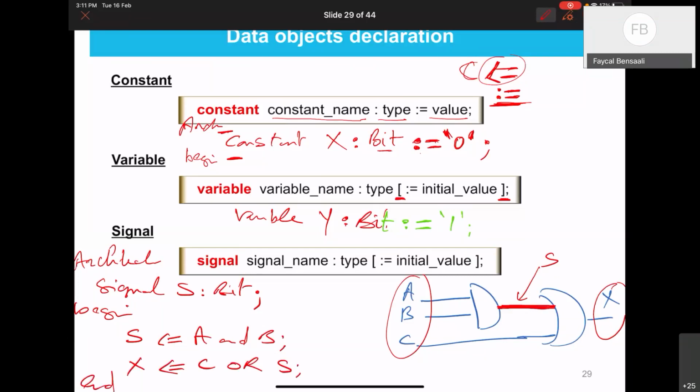So you can have all of them in one line. I can separate them like this by having signals. Right? Sometimes you may need to use signals. So for example, if you have inputs like this, outputs like this, Y, you may need to use this line Y here. So you need to declare this as a signal and then you use it. And both solutions are correct, as I said. Is this clear? So this is what we mean by a signal. We don't have this in C or C++, right? So this is related to hardware.